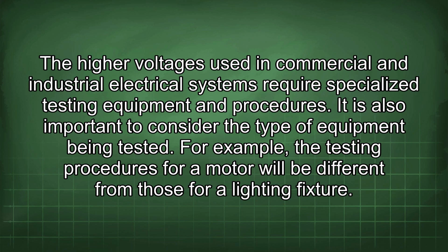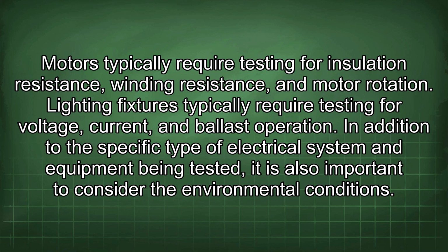It is also important to consider the type of equipment being tested. For example, the testing procedures for a motor will be different from those for a lighting fixture. Motors typically require testing for insulation resistance, winding resistance, and motor rotation. Lighting fixtures typically require testing for voltage, current, and ballast operation.